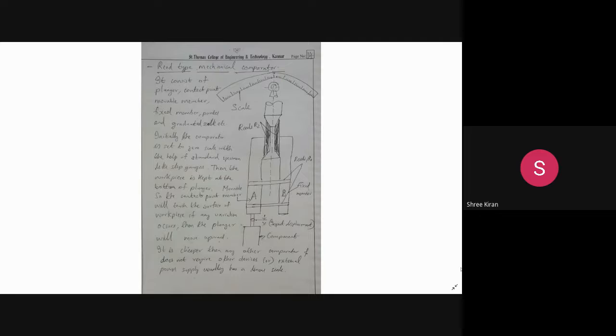Yes, that's right. The standard deviations. A slip gauge is a small bit of metal where the dimensions are already marked, right? So when the dimensions are marked, we use an instrument, in some cases a vernier scale, micrometer, or dial gauge. Many instruments were calibrated. Calibrated means we already have a set value in the slip gauge, and by measuring with the instrument, we find the standard deviation. That deviation is marked, and then we calibrate the vernier scale and everything. Do you remember?